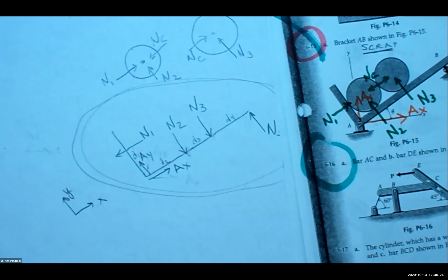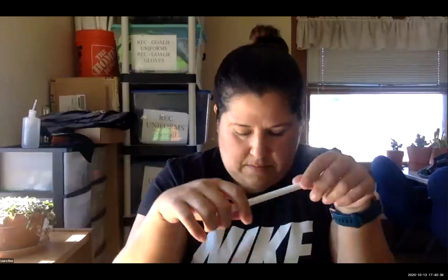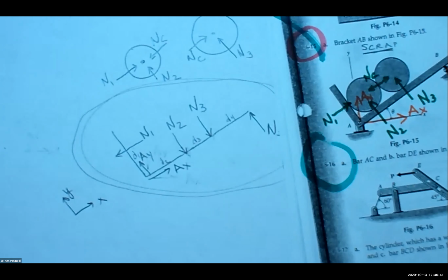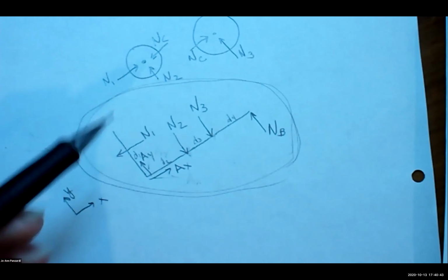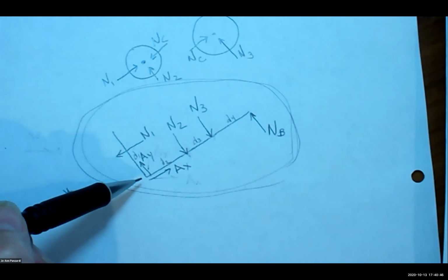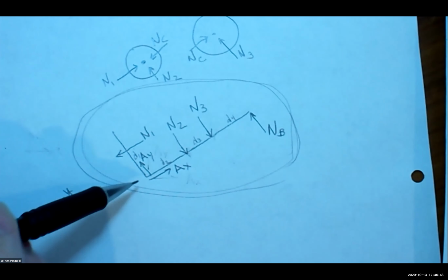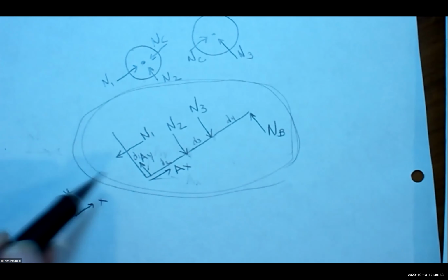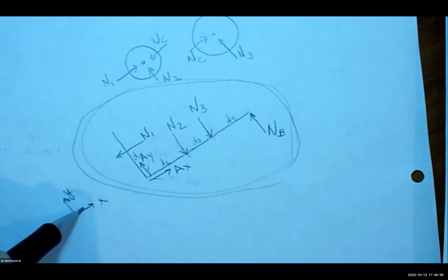It doesn't matter how I put AY and AX, because when I get the values of it, I'm going to know what directions they're going in. Is everybody comfortable with that? Did I just confuse people? Rotate your axis to simplify the amount of math you have to do. So put your AX and AY along the axes that you're choosing.